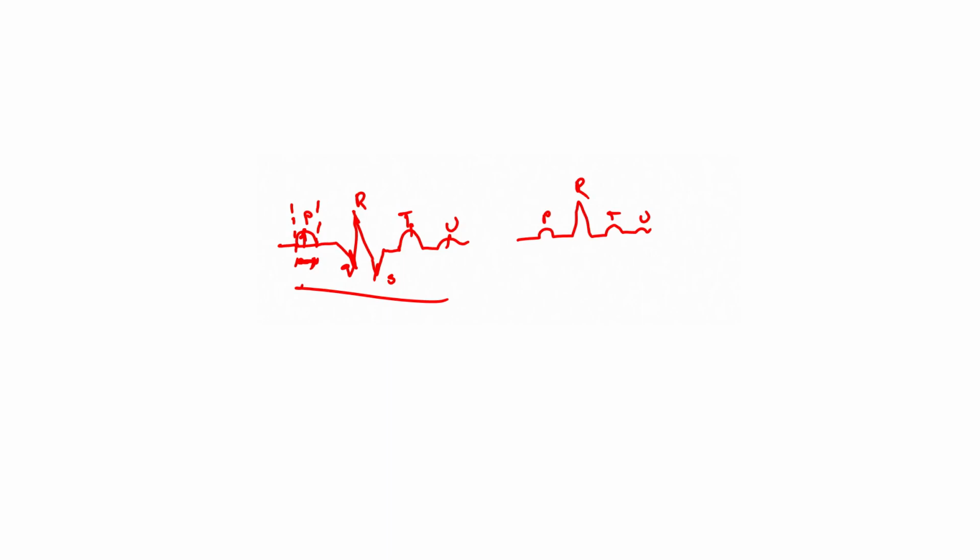So, our whole idea is to find out BPM, again remember that. Now, from the signal, how do we calculate only the peak of R? If I want to calculate only the peak of R, I have to understand how to differentiate between a peak and a point. When I digitize the signal, we take different samples at different intervals, but how do you decide that a particular value is a peak?